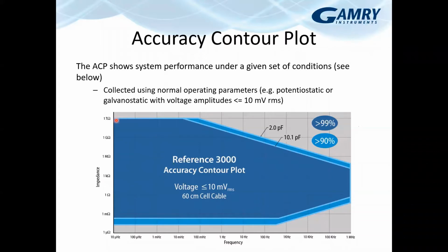You can make lower current ranges, but when you get to the point that you're dominated by thermal electron movement, it doesn't really help you to go lower. Additionally, you've got the printed circuit board resistance, which puts a limit on what you can actually do, no matter how many ranges or gain stages you put down there. So at some level, you're theoretically limited by the printed circuit board itself, and we're getting pretty close to that up at the teraohm level.